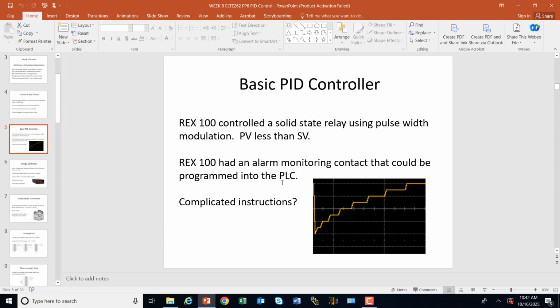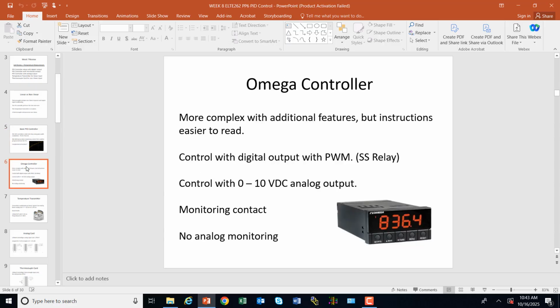The way that these work, you can have a set point, and then you can have a dead band of plus or minus 2 degrees, or plus or minus 4 degrees, or plus or minus 1 degree, versus are you setting a high limit and a low limit? Is your dead band being set with just the high limit and low limit to have it go back and forth? So when you're setting up a controller, hopefully that makes sense, you might be looking at it 2 different ways: one just has a set point and then you give it the dead band, or the dead band is dictated by a high and a low.